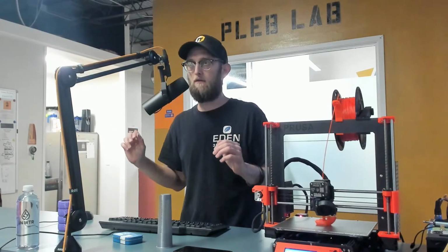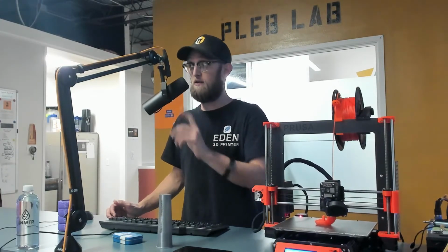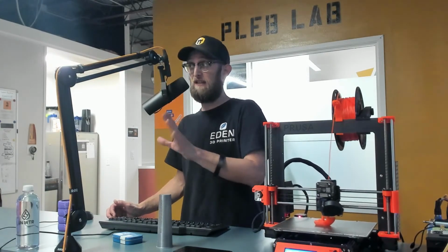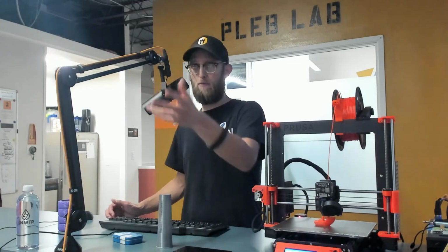Put it in the oven at 100 degrees for like 2 hours, or 90 degrees. Honestly, the lower the better for longer, just to make sure it doesn't warp, especially for PLA, mind you. PLA needs to be more like 70, 75 degrees, maybe 80. You don't want to get any hotter than that. But as long as you're in that right mindset to say, all right, this has been sitting out for 2 or 3 months, I can put it in the oven, or I can put in some rice for a week or something like that. That would suffice.